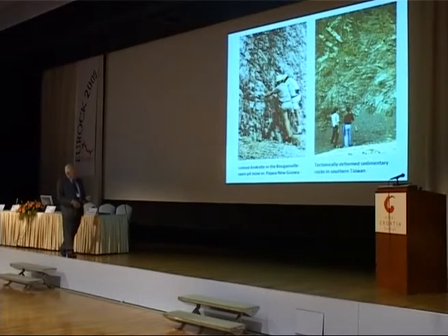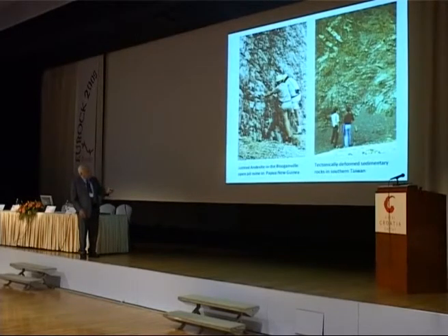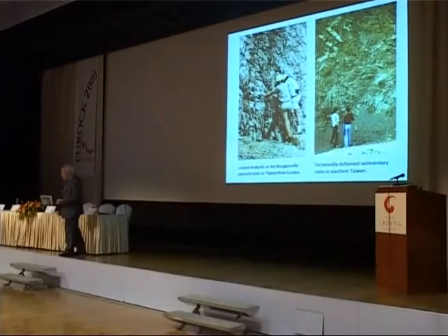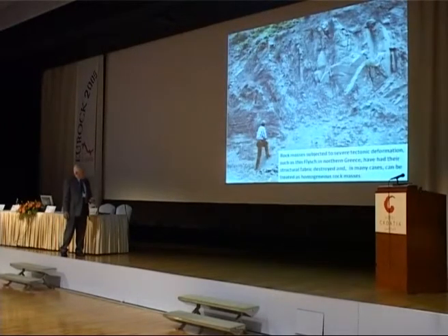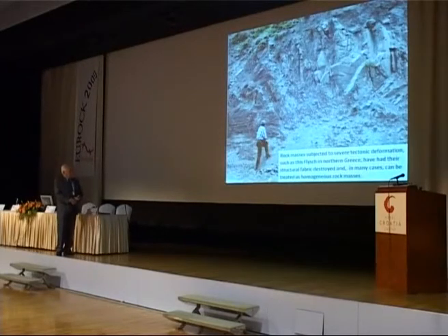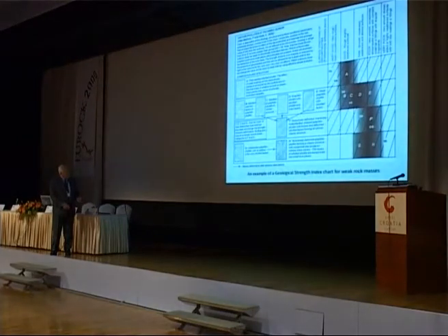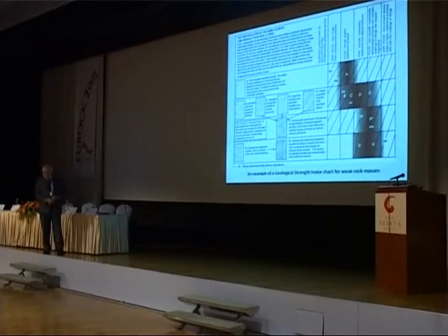And at the other end of the spectrum, this is in Taiwan, where the rock has been so tectonically deformed that the structure is effectively destroyed. In Greece and in many parts of the Alps of Europe, you have Flysch, which has been very severely tectonically deformed, and where, as a reasonable approximation, this can be treated as a homogeneous system. This led in Greece to the development of, although this one is for Venezuela, a classification system to try and describe in a qualitative way how the tectonic forces have changed the rock mass behavior.